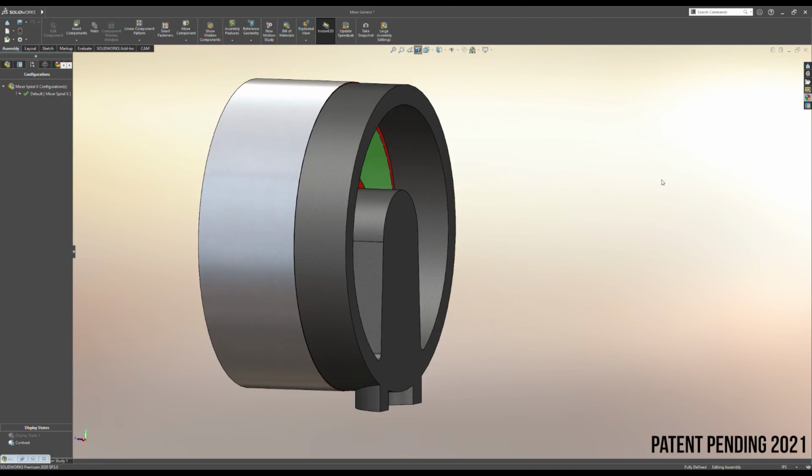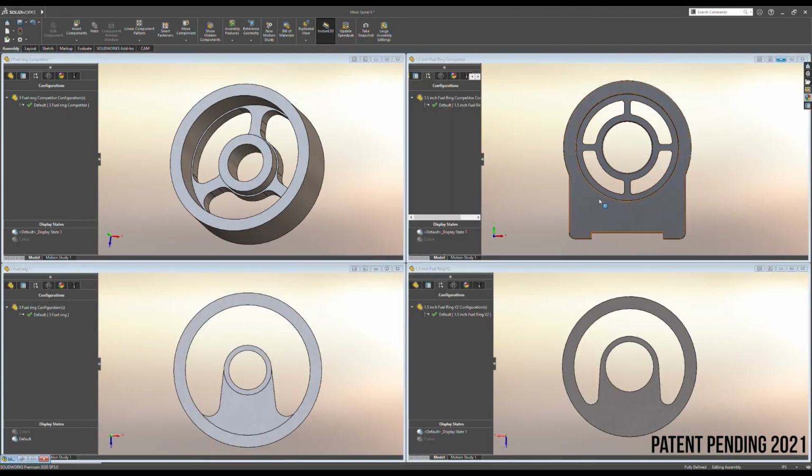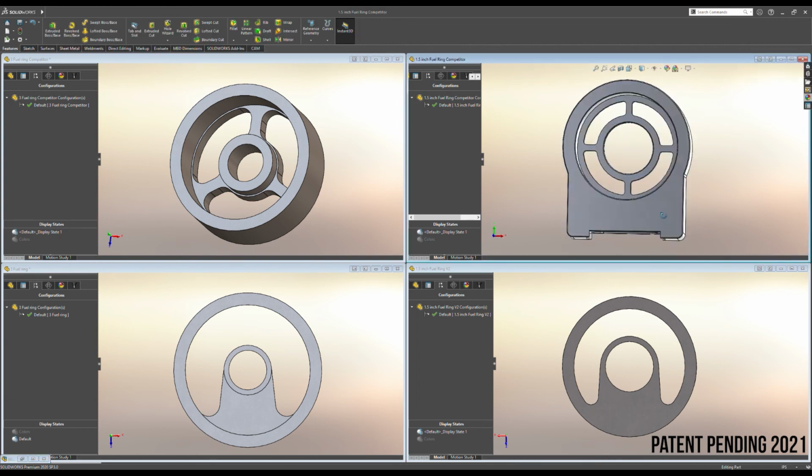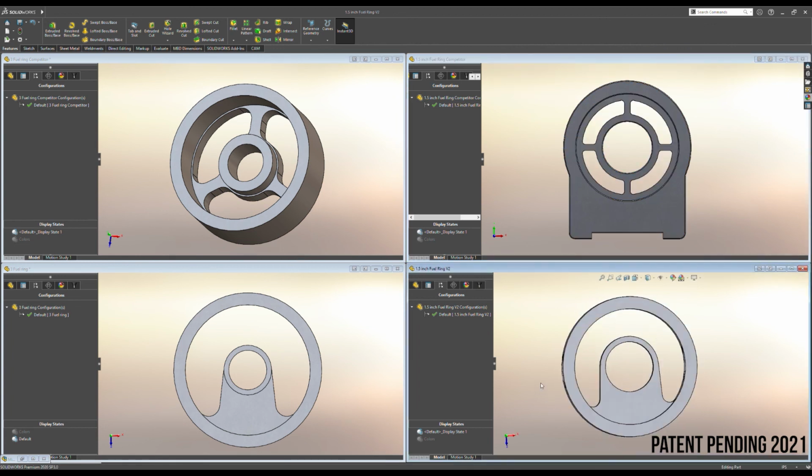So if we go back to these fuel rings here, the smaller diameter fuel rings, it gets even worse, the 1.5 inch, for example. This is a generic fuel ring design you might see for a 1.5 inch mixer. We have improved our surface area and cross-sectional area from this design to our design, which improves by 68%, almost 70% more cross-sectional area to improve airflow and therefore reduce emissions.